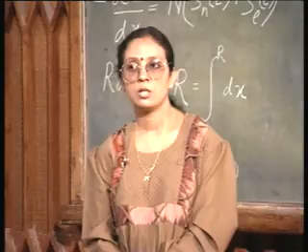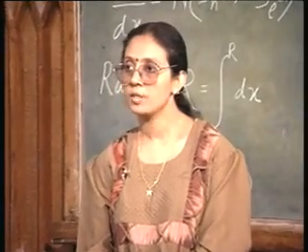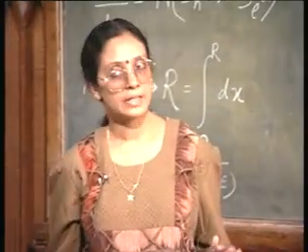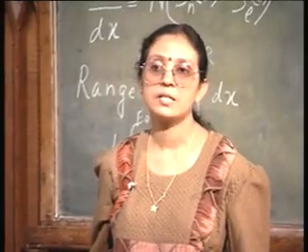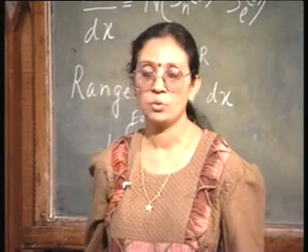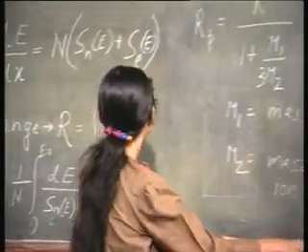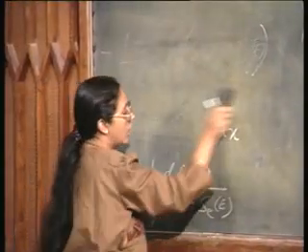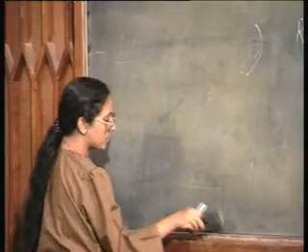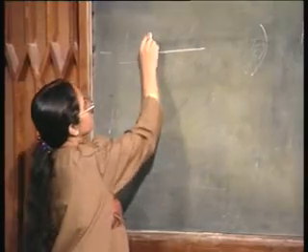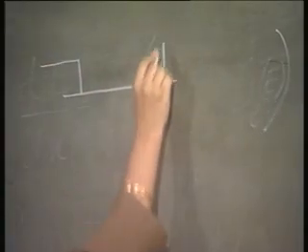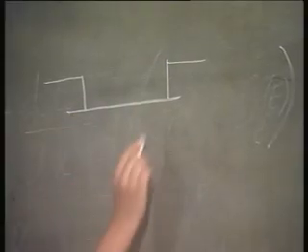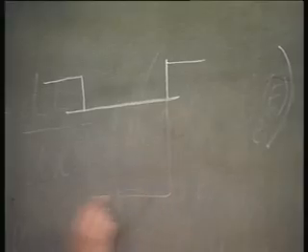So, this is about ion implantation and how the incident beam is moving inside the semiconductor. But again, just as in case of diffusion, you know that if I have a window like this, ideally speaking, I would expect the dopants only to move like this.